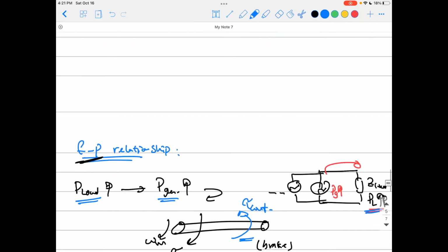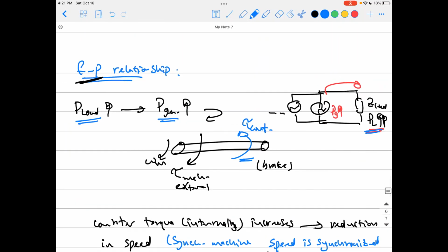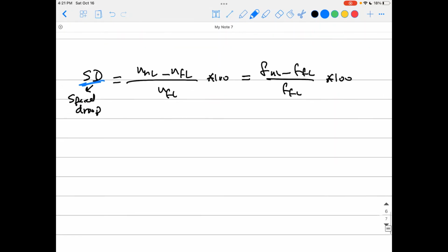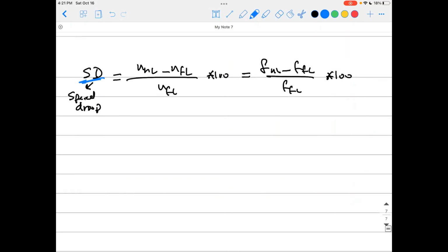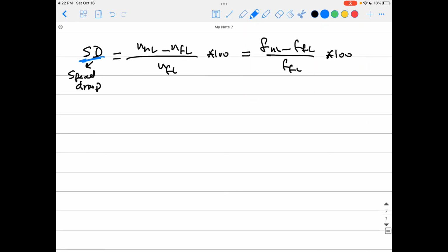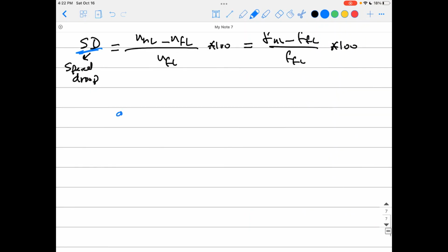So it's the same idea here. If the active power requirements of the load change, it will impact and change the frequency of the machine, and we don't like this. We have to maintain the frequency output of our machine at its rated condition. Here in North America, we're talking about 60 Hertz. So we need to maintain it at 60 Hertz, otherwise it will harm the loads connected to the generator. So like we had an AVR, an automatic voltage regulator, to sense the change in Q requirements and restore the terminal voltage by controlling the excitation, we will have another controller here. We call it the governor.